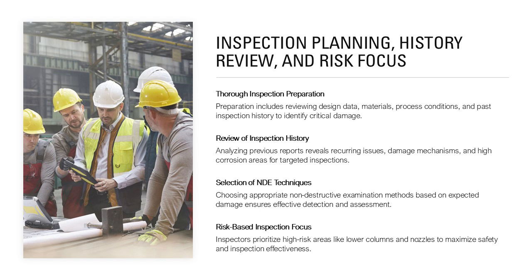Input from operations, process engineering, and corrosion specialists can help inspectors understand current operating challenges, process upsets, or changes that may influence damage patterns. Inspection planning should also include development of an inspection scope and non-destructive examination (NDE) plan. This involves selecting appropriate inspection techniques such as visual examination, ultrasonic testing, magnetic particle testing, liquid penetrant testing, or radiography based on expected damage mechanisms.